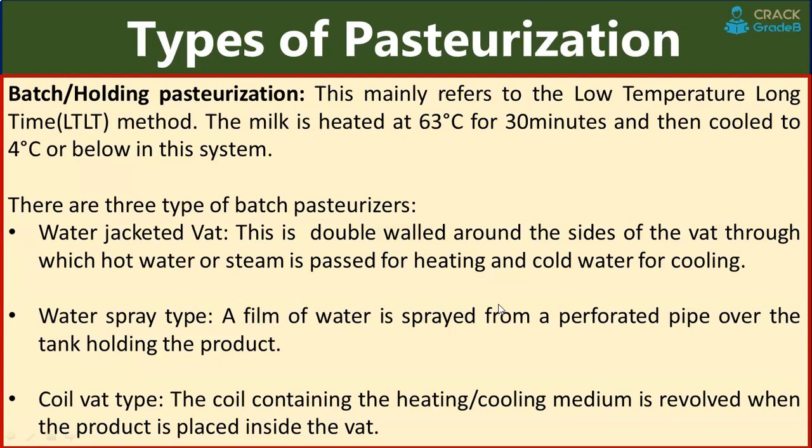Next one is the water spray type. A film of water is sprayed from a perforated pipe over the tank holding the product. Third one is the coil vat type. The coil containing the heating or cooling medium is revolved when the product is placed inside the vat.